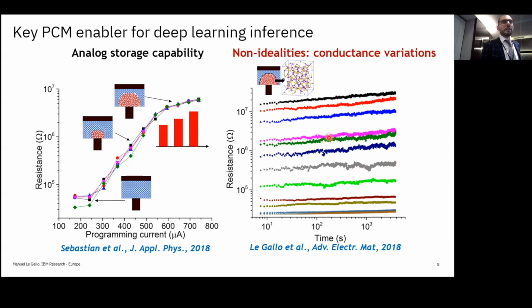The drawback is the drift. The drift is not as present, I think, in ReRAM or other devices. And the noise also is not small in PCM. Another thing that is not great about PCM is that it still requires fairly, not crazy high voltages, but still something like 2 volts to reach the threshold voltage at which you can pass enough current to program it. That is a bit of a problem when we want to increase the density,